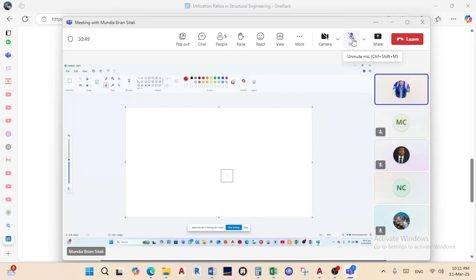Yes, it will. So for engineers, we are sometimes limited by architects, because the architect will say, I don't want a column that is larger than 200 in width, because I want the column to be hidden in the blockwork. Then you have to know what to do as an engineer to make that satisfiable. If you give the architect a 400 by 400 column, and he wants the columns to be hidden in the blockwork, you will fight over that. So you just use the same 200 by 400 that he requires, and just reduce your spans. If you have double the number of columns, well and good, but you have satisfied his aesthetic pleasure.